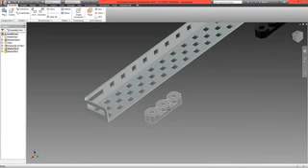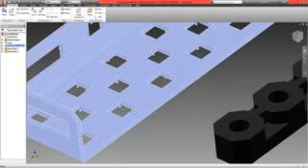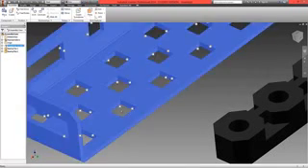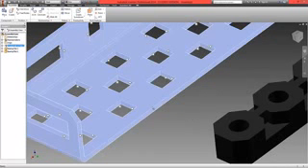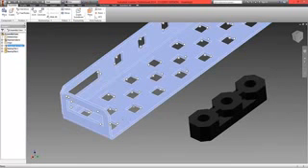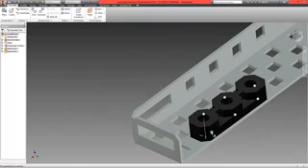To begin with, we're going to click on this metal part here, and as you can see there are balloons which reference the top surface and the bottom surface of these squares, and these squares will allow you to fit circles, so we have an insert function being created. So we're going to use this feature now. First of all, select the top balloon, hold down Alt and select it, and we're going to match that to the corresponding balloon here on the bearing.